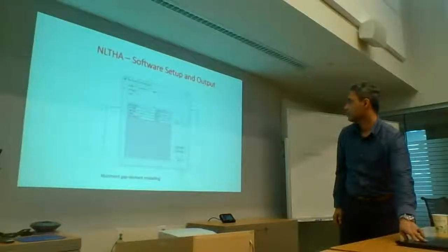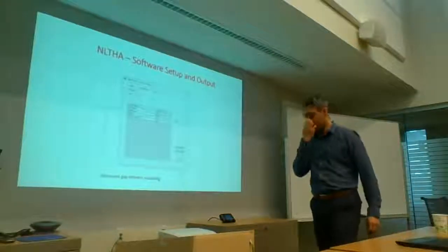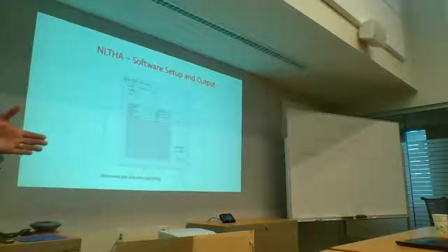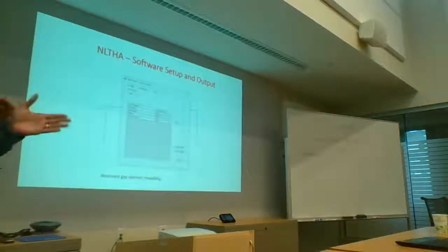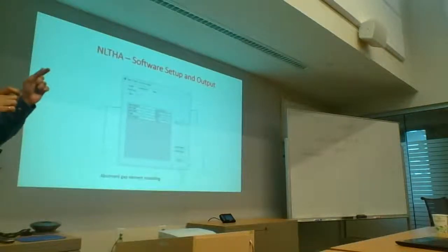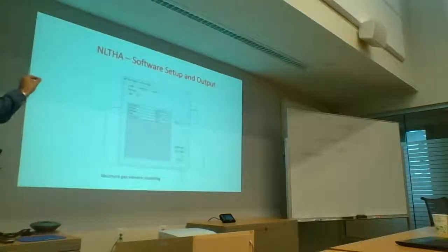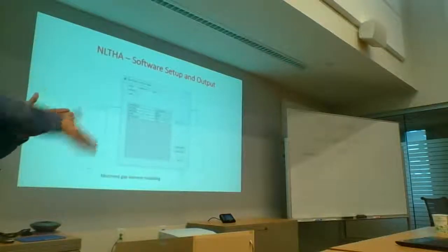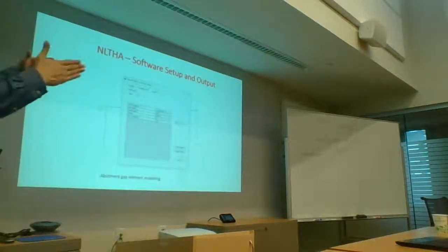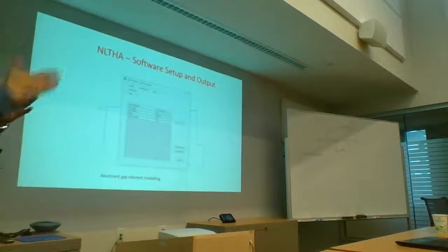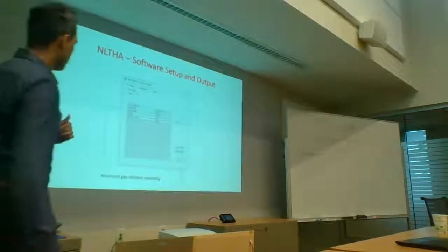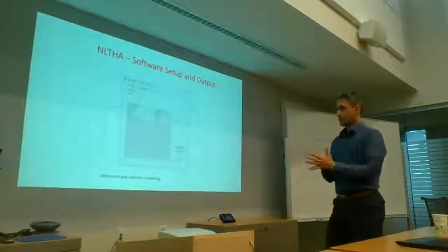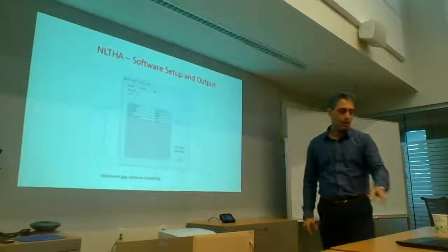What I want to show you is, we had a gap element here, because this is a nonlinear time history analysis. That's the beauty, right? I don't have to iterate in any way. I can just give the nonlinear spring property to the program, and I can say, look, this has a gap of so many mils, and only after that its stiffness kicks in, and then it goes flat at this displacement, and it's just going to find that out for me. So over on this side, I think we had a standard abutment with gap, so we modeled that.